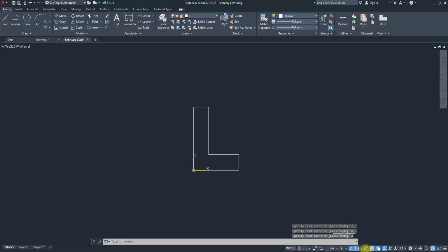So you see that? We've created this L shape using the absolute coordinate system. Let's try relative rectangular and see whether we still get this L shape. I'll move this UCS icon. Select it. We looked at this on Wednesday. Once you select it, bring your mouse to this square icon, click it and go somewhere else. Let's say I want it to be here. I'll click. So this becomes my new coordinate system. Anything I start now will snap to this place.